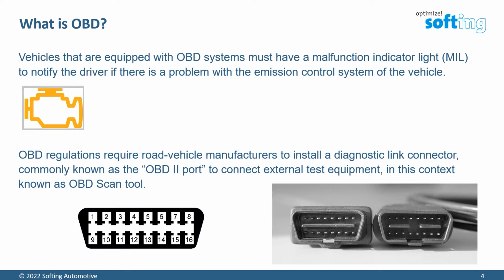Vehicles that are equipped with OBD systems must have a malfunction indicator light, a MIL, to notify the driver if there is a problem with the emission control system of the vehicle. OBD regulations require road vehicle manufacturers to install a diagnostic link connector, commonly known as the OBD II port, to connect external test equipment, in this context known as OBD scan tool.